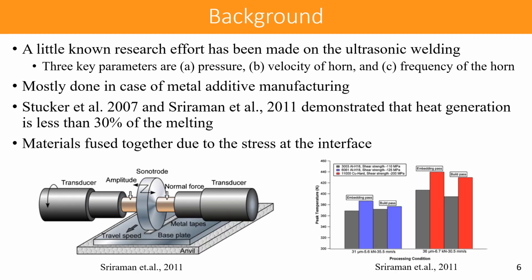Lately, we can see that similar technology has been used in additive manufacturing, known as ultrasonic additive manufacturing technology. The way it works is that you have a stationary build platform and stacked sheet metal, and the ultrasonic vibration on the sheet metal fuses the sheet metal together and creates the solid body.